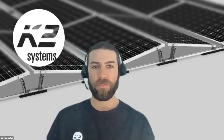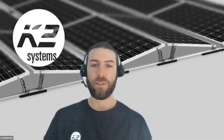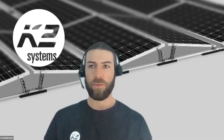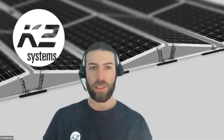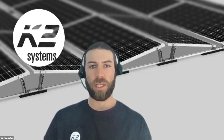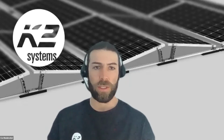And as Karen said, I work in Switzerland and we have very high snow loads. If you have a roof tilt that is not very steep, let's say 20 or 15 degrees, you obviously need more stable roof hooks than you would in Germany for a 15 or 20 degree roof. Yeah, yeah. And I'm assuming that this type of system would be compatible with trapezoidal roof types.